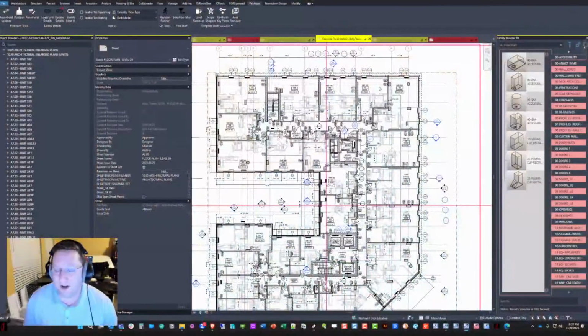So this building, being more of a garden style, is not like a stick-built exterior wood wall with windows. In garden style, there's a huge propensity to want to put exterior windows in the model group. Well, you can't, because the exterior wall doesn't go in the group. It can only go in the group if its host is in the group. That goes even more strict for face-based families. Face-based families should not go in the groups at all.